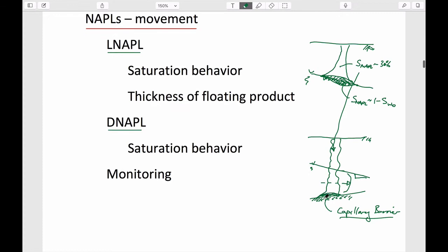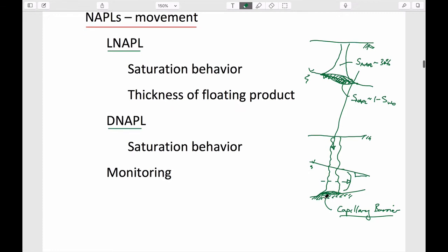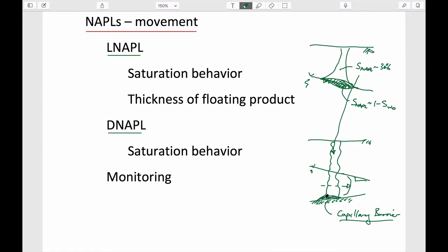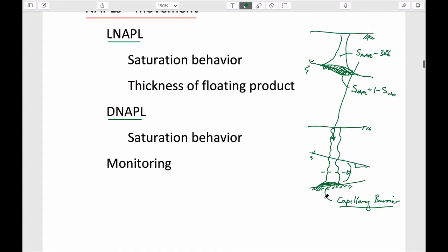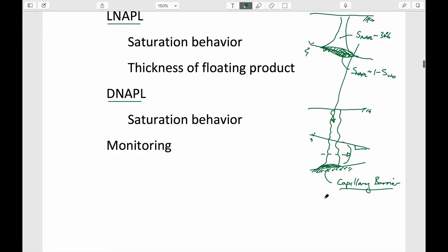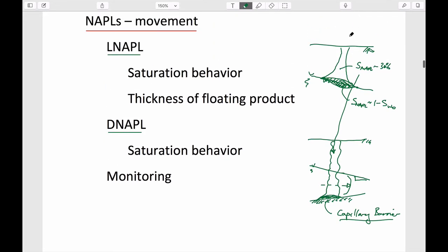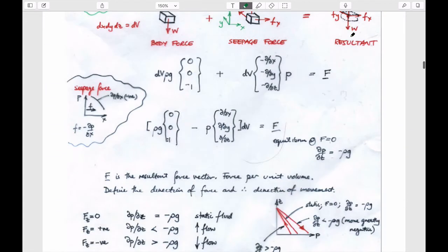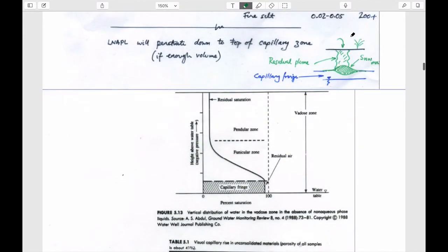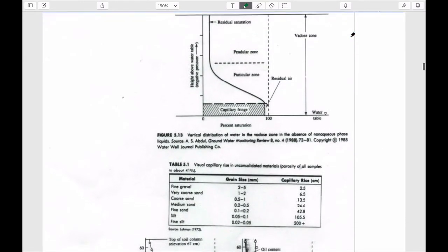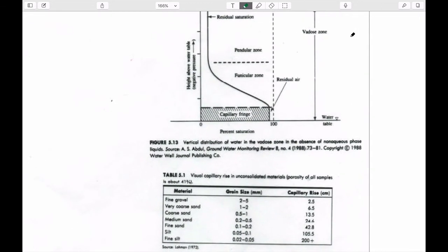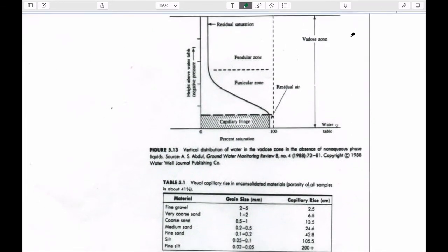So let's talk about exactly what, from our understanding of these two very important component behaviors, most important of which I guess is the capillary pressure versus saturation curves, exactly what we think the saturation distributions might be in each of these cases. So that's what we'd like to look at, what those would look like on graphs per se. And so this is the key view, I think, of that. We know that, and this is out of Fetter, so you've seen this elsewhere.